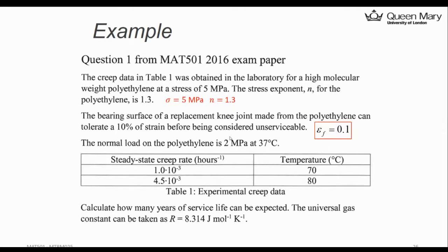And the normal load on the polyethylene is 2 megapascal at 37 degrees. That's your human body temperature. I hope you didn't exceed this temperature at this moment. Okay, that's a joke. The normal stress on the polyethylene in service life is 2 megapascal.